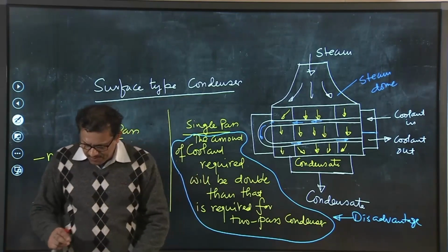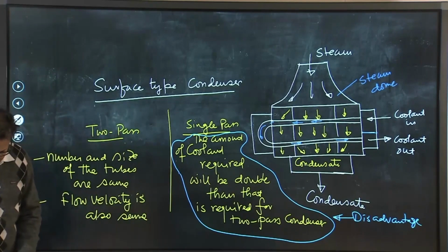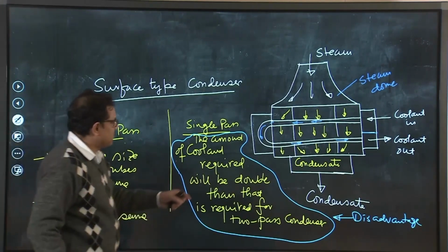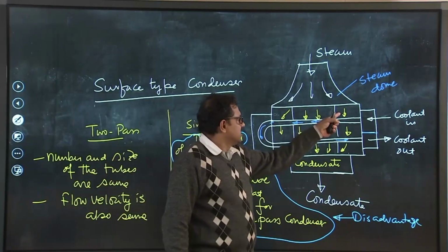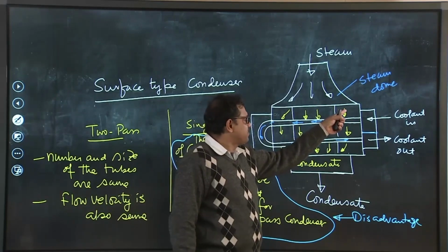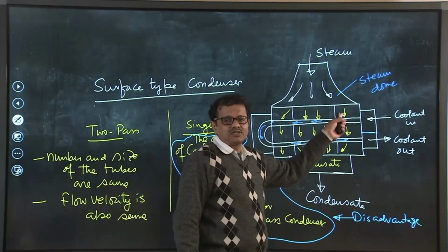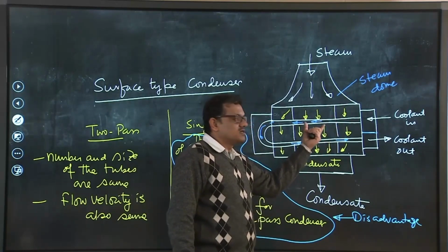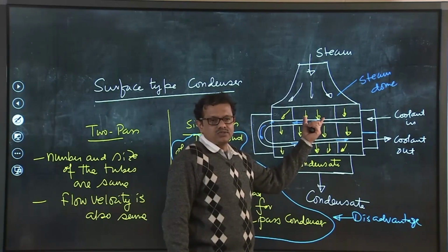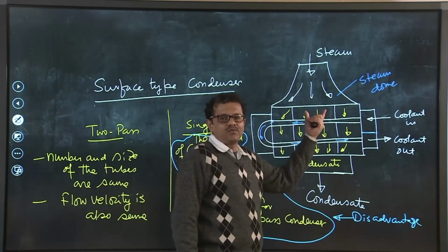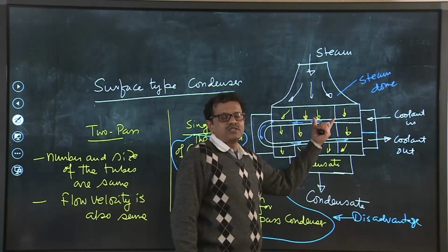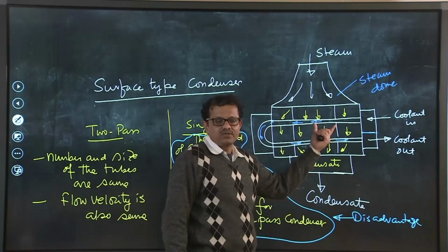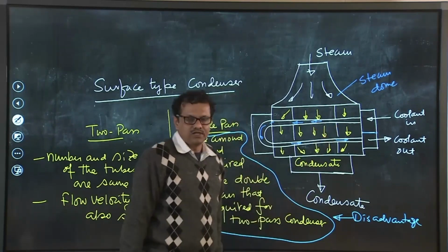Number 2 is, so this is very important point, if air leaks into the condenser through different joints, then the vacuum will be reduced. So, the pressure at which condenser is operating will go up. So, that means the turbine back pressure will go up and turbine work output will be reduced.